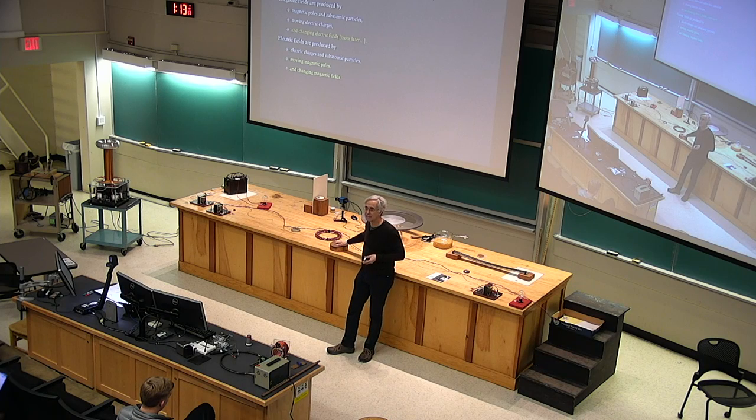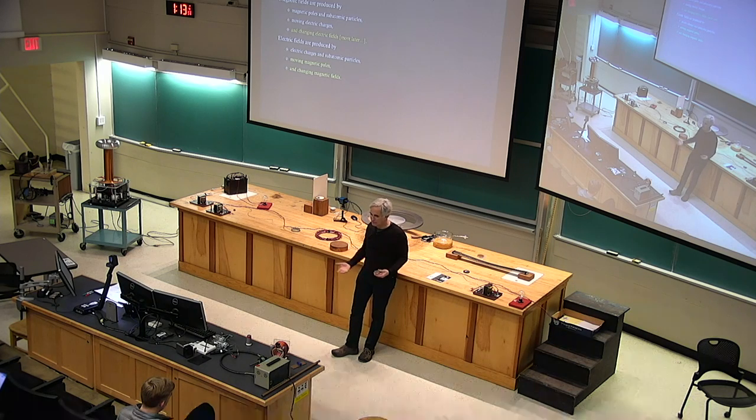If I create an electric field in the copper, current will flow through the copper. The current won't light any light bulbs because there are no light bulbs around, but that current will become magnetic. It'll produce its own magnetic field, which will interact with this guy's magnetic field, and they will fight each other again. That is, it will fight any movement of the magnet that creates that current.